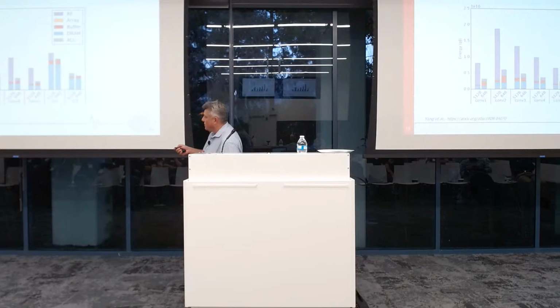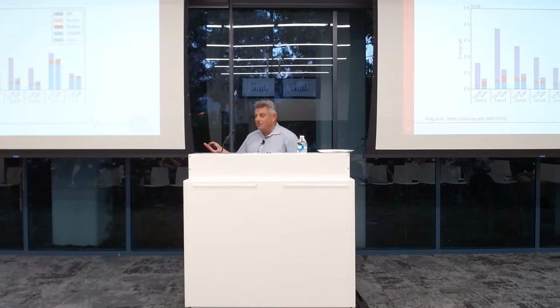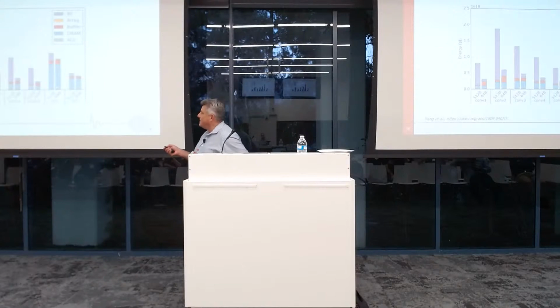If you make a large register file versus a small register file, the problem with large register files is that you have a lot of capacitance hanging on each bit line. So you're actually dissipating a lot of energy every time you access this, and this is why these bars look so terrible. And one of her contributions for a PhD thesis was to figure out what the optimal register file size is. She figured out that 64 bytes is enough, and that makes much smaller capacitance. And you end up with a much more balanced energy profile in the memory architecture.